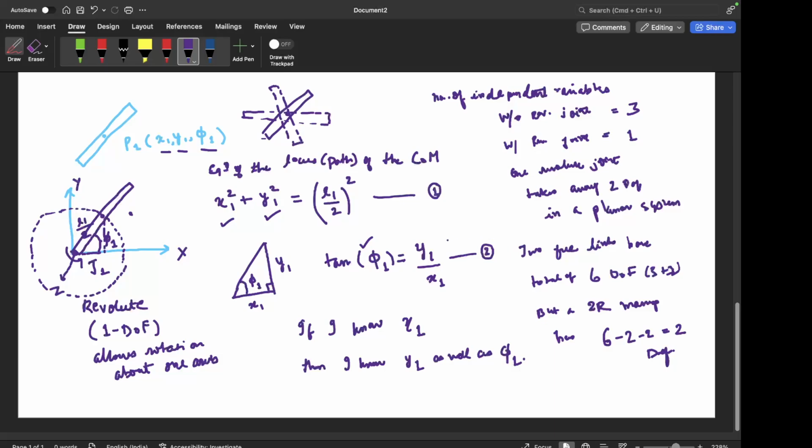After you have studied many such systems, and you have spent some time working with different kinds of robots, then you start counting degrees of freedom in a more intuitive way. So in this case, two revolute joints, that is 2 degrees of freedom. Usually the natural choice of independent variables in this case would be phi1 and phi2.